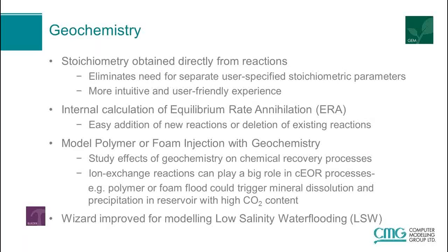The first one is that stoichiometry is now obtained directly from reactions that you input, meaning that it eliminates the need for a separate user-specific stoichiometric parameter definition. And this makes things much more intuitive, user-friendly, decreases the amount of work you need in setting this type of model up.